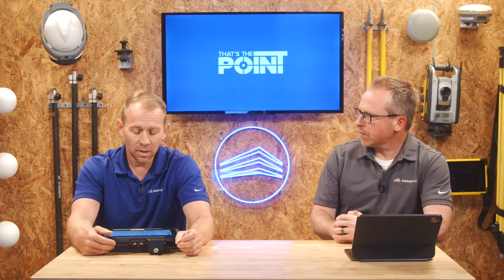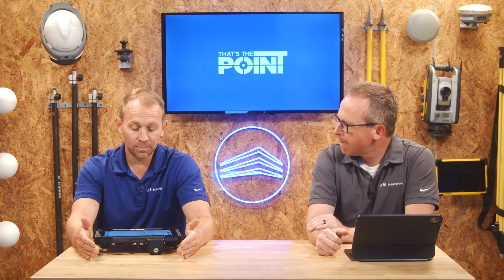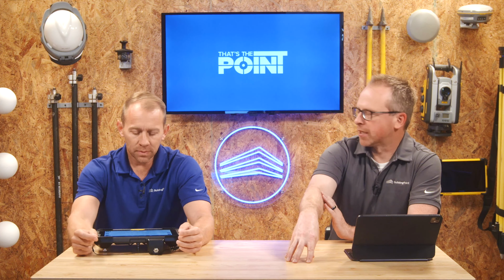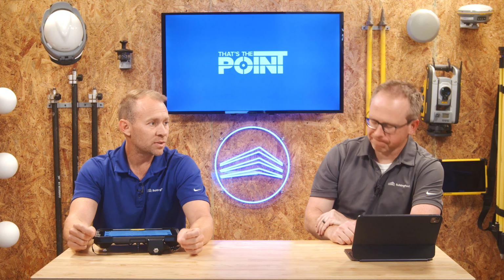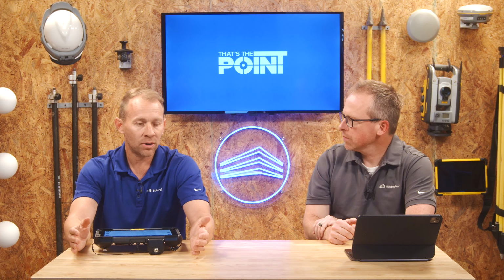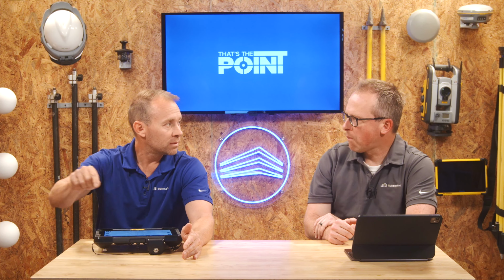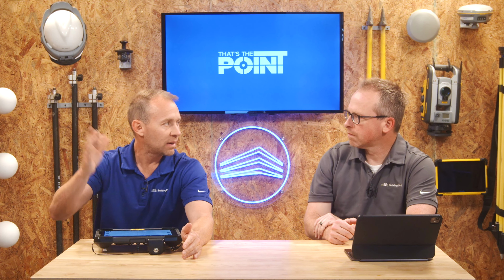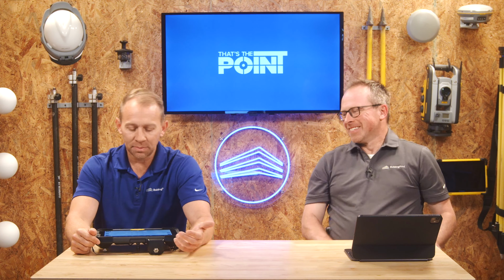Yeah, absolutely. And really what this is about is when we have to create data that our guys in the field may not have, or in addition to what's in our file for what we're laying out. Right, you might have just a center of column, but you don't actually have your bolt pattern out there for the anchor bolts or something. Right, correct. So this allows us to create a pattern of points that we know is consistent, that we can just pop in wherever we want instead of having to keep manually offsetting 500 times or even 20 times. Even 20 times isn't fun. Right, absolutely. That makes sense.